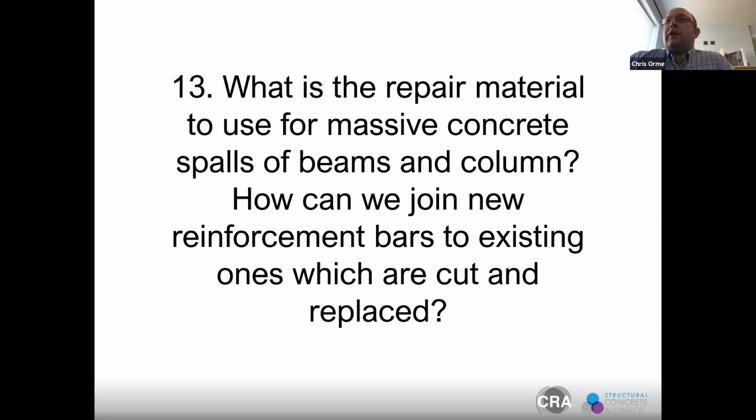Thanks, Paul. Yeah, you have suitable resin systems you can use to bond or connect to ties as well. But I think, coming back to the repair materials, what method you use depends on, obviously, the size of the repair, the location and the environment as well. You might have a tidal area or something like that. So you might not be able to use a traditional hand applied method, or you might need to use rapid setting materials and things like that.